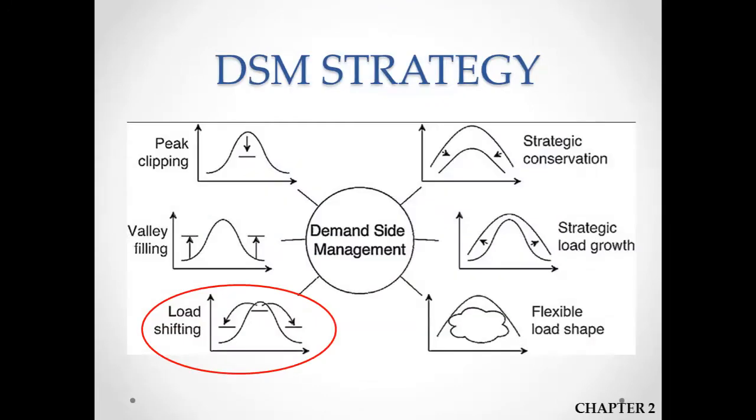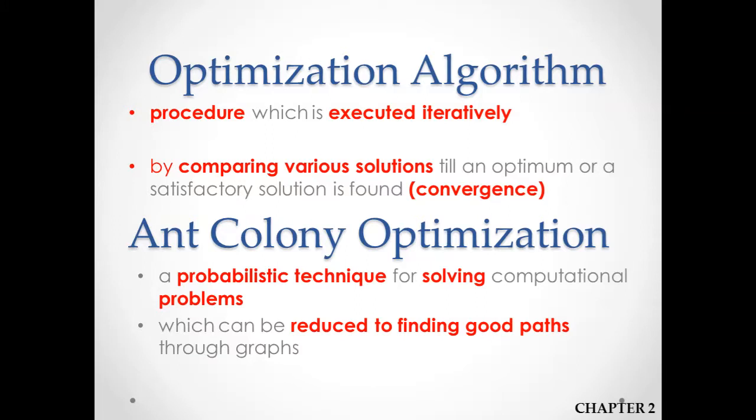To reduce the electricity bill in TOU tariff, a demand side management technique such as load shifting is needed. Load shifting is basically shifting the energy consumption at on-peak zone into off-peak zone. By this, the higher cost per kilowatt hour can be slightly avoided. The optimization algorithm is needed to find the optimal cost and load profile.